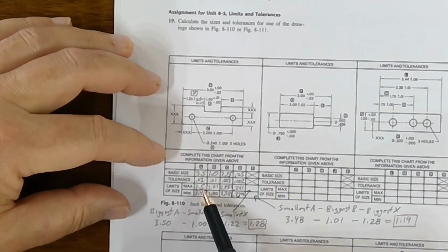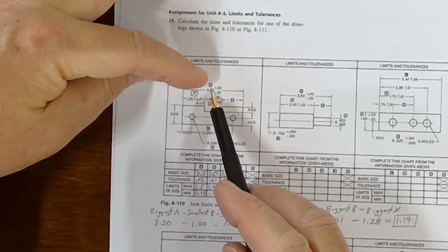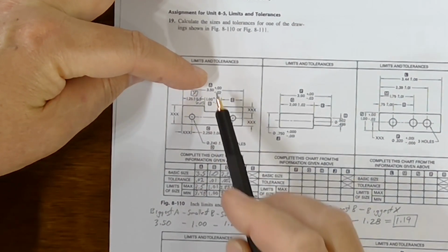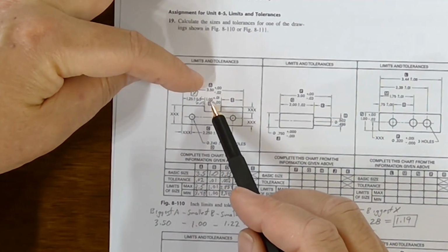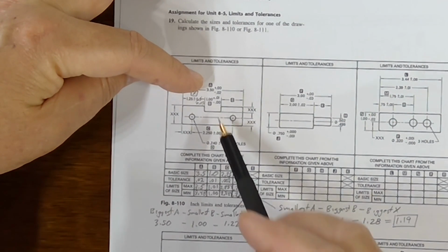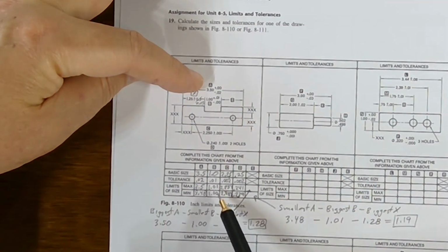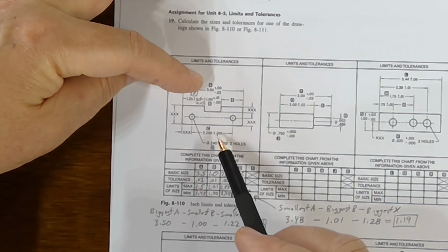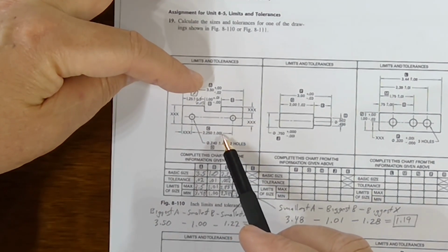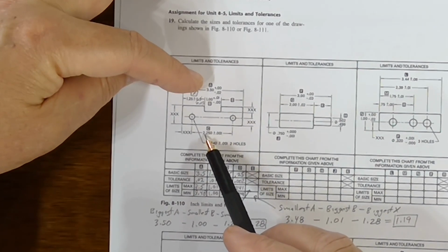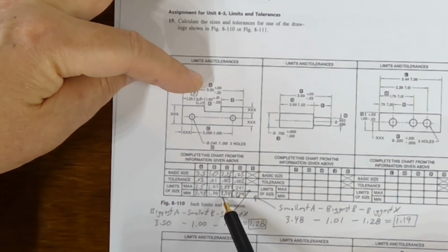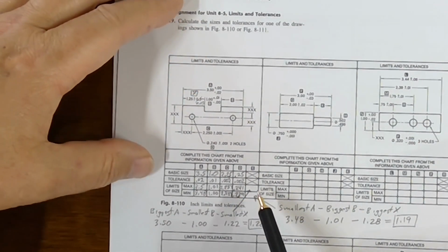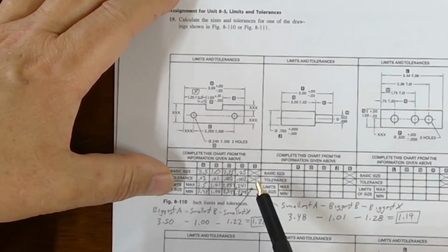Okay, then what is the min and max value? So A, the max it'll be is 3.5 plus 0, so 3.5. The min that it could be is 3.5 minus 0.02, so 3.48. Okay, for B, the biggest it could be is 1 plus 0.01, so 1.01. And the smallest it'll be is 1 minus 0.00, so 1.00. This thing here, C, could be over and under by 0.001. So the base dimension is 2.25 or 2 1/4. So it's going to be 2.251 and 2.249, right? Over by 1 and under by 1. So like that.